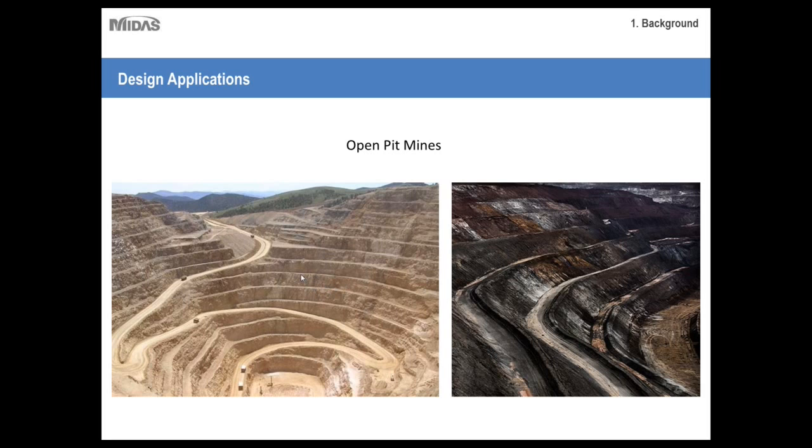But because we wouldn't want any failure to occur, it's always a very good rule of thumb to check for the stability of these various slopes, and also to check for structural weaknesses within the rock, such as faults, shears, joints, or foliations. Those are important things to consider when constructing these open pit mines.